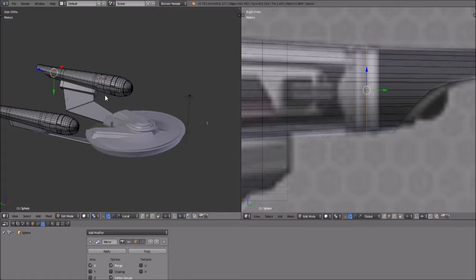So we've got to put in a lot of extra edge loops, and when we apply the subdivision surface modifier, we're going to get a lot more edge loops, which is going to greatly increase our vertices, edges, faces, all of our little multipliers up here. It's going to greatly increase those, but we can always go in and clean up the ship post modeling.